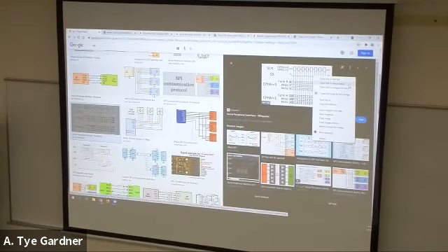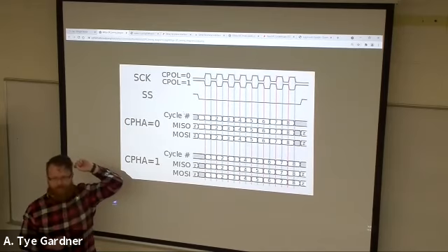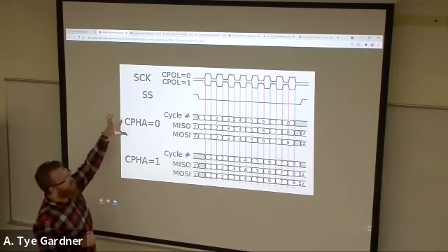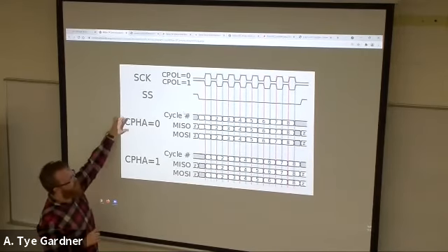And then we need to determine where we're looking to sample. So let's look at this one. CPHA is 0 and CPOL is 0. That is mode 0,0 for SPI. There are 4 modes: 0,0, 0,1, 1,0, 1,1. Let's look at 0,0 because I'm pretty sure that's the one we have to build for our data sheet, or sorry, for our controller that we're doing in the lab.